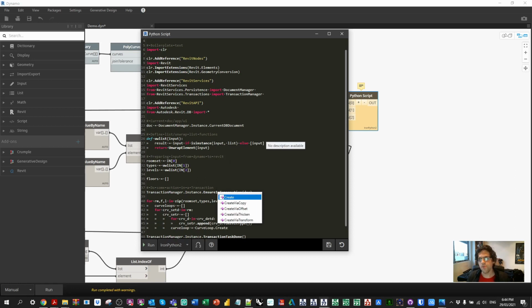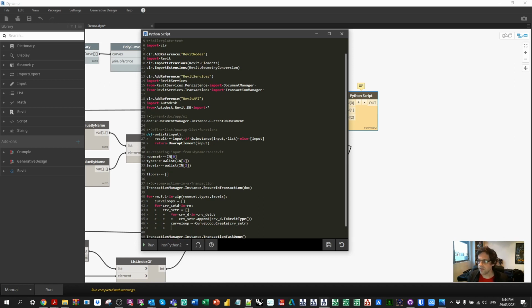So in this case, I am generating a static method. I'm creating an element from a function. And I'm going to be doing this based on, in this case, my set of Revit curves that I've defined previously. So I'm taking these curves and joining them into an element that the API understands. And then for each of these that I've generated, I'm going to be appending these together. So I'm going to be appending these back into my original list of curve loops that I made a little while ago, a few levels higher.